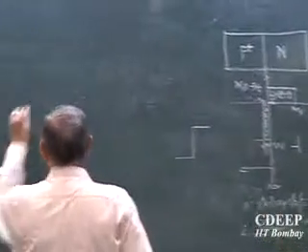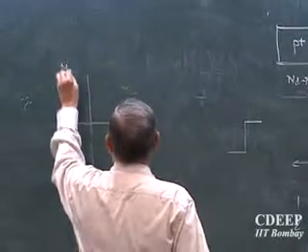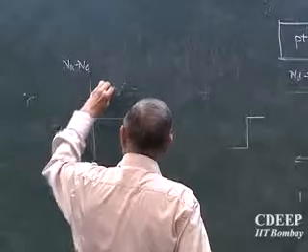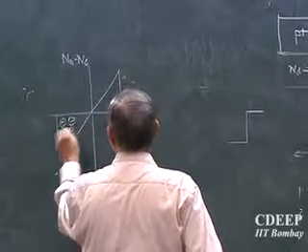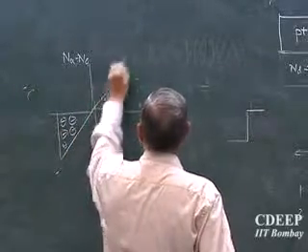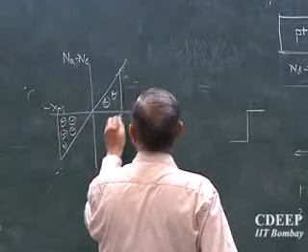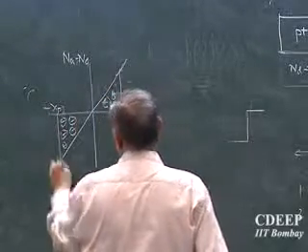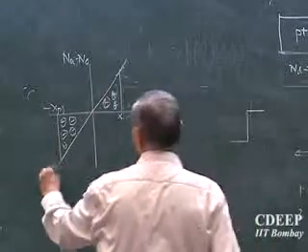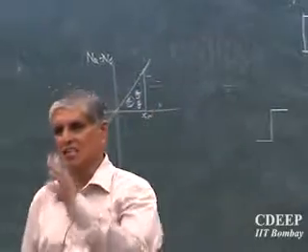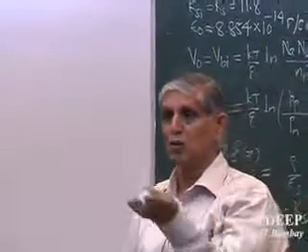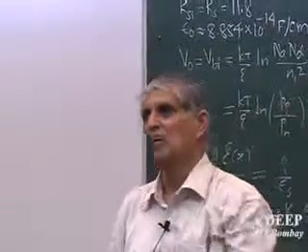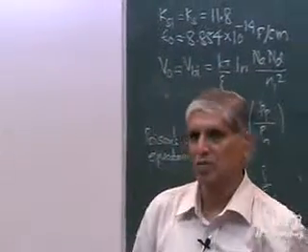However, there are other possibilities. If I plot Nd minus Na, which is minus xno, which is xno, what does this mean? It is graded linearly. It goes from P to N linearly. So Nd minus Na is proportional to the gradient itself. We call the grade constant D, that is the slope of this curve. These junctions are called linearly graded junctions.